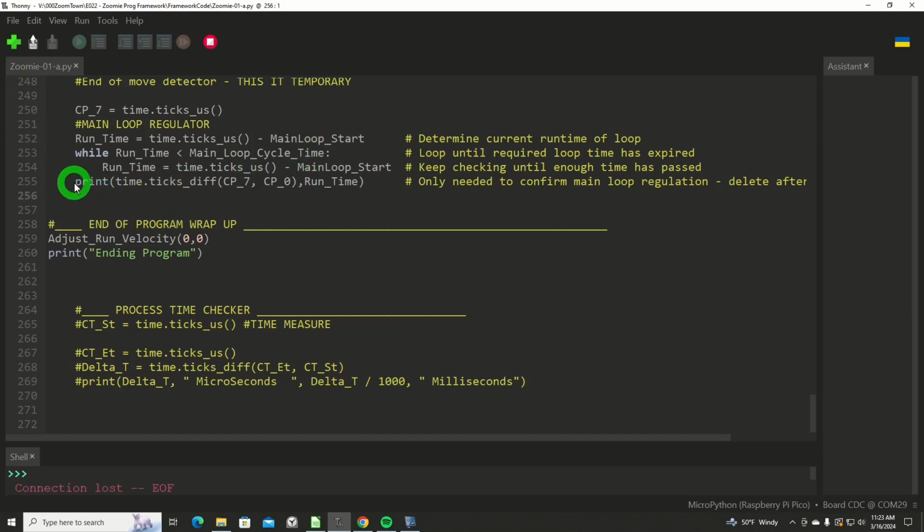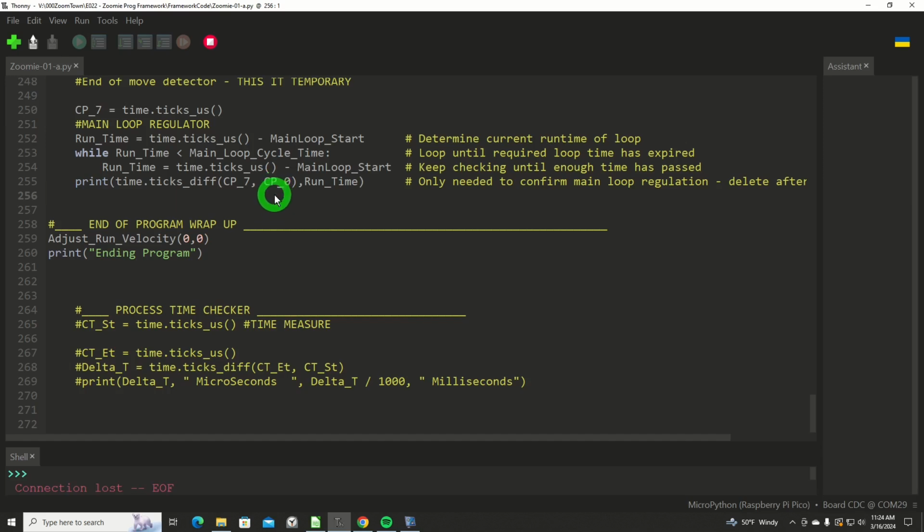And then most of the time, I'm printing out that time difference between those two so that I can make sure I am running truly deterministic. If this value that I print exceeds 5, then I know my loop is running longer than the 5 milliseconds. Now in truth, because of the time to execute that, there's microseconds of time wasted, and I'm not overly concerned about 10 or 20 microseconds because of that. So yes, I am aware some of these things aren't absolutely to the microsecond accurate, but I am getting exactly what I want. And we'll see that run here in a minute.